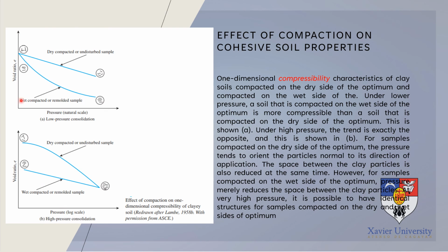Actually, this illustration is related to the pressure. It is actually the unconfined compression test of our soil, UCS. What it means is that if our moisture content is lesser, as our moisture content increases, the compressibility of the soil also decreases. And after reaching its optimum moisture content, any increase in the moisture content beyond the optimum will now increase the compressibility of our soil.